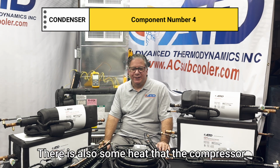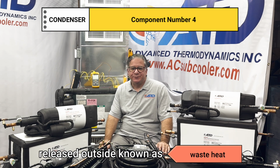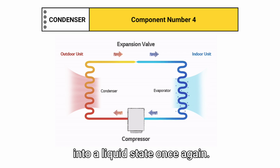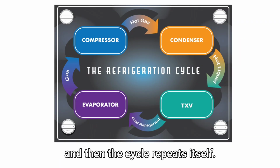There is also some heat that the compressor introduced into the system that is also released outside, known as waste heat. As the refrigerant travels through the condenser, it cools down and condenses back into a liquid state once again. This liquid is then sent to the TXV once again, and then the cycle repeats itself.